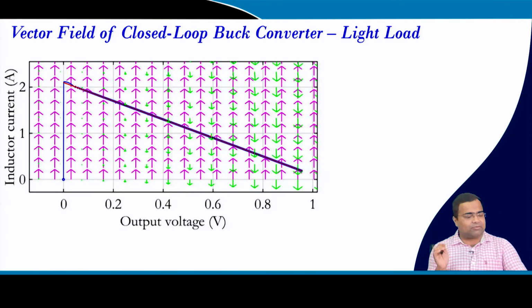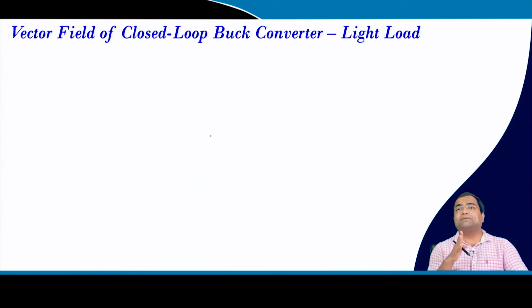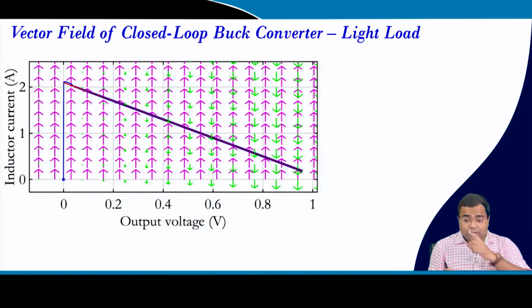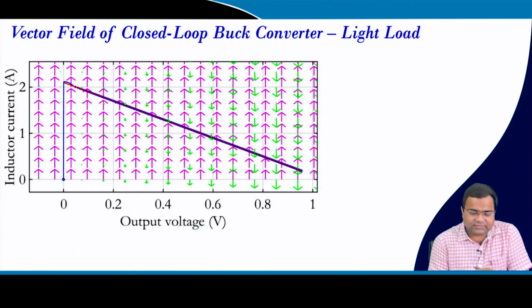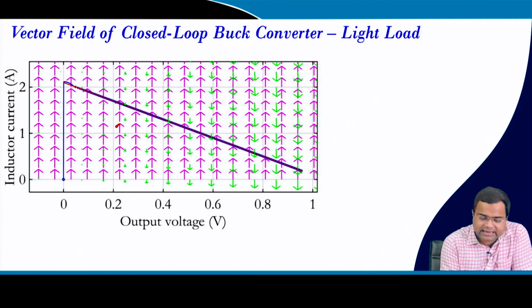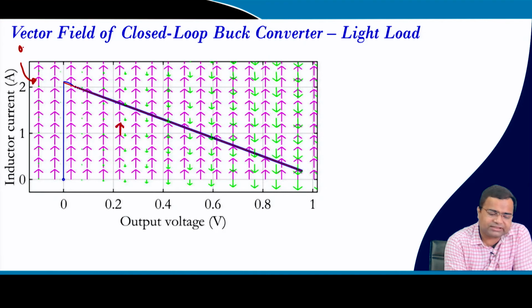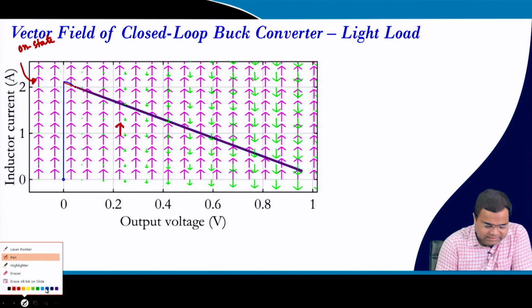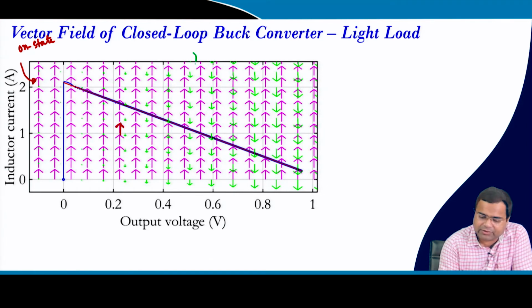Now, again coming back to the question: how to obtain, I want to make sure my whole trajectory will look like an eigenvector. That means, if you see here, this line indicates our on state trajectory, that means this particular color is the on state trajectory, and if you see the green one, these are the off state trajectory.